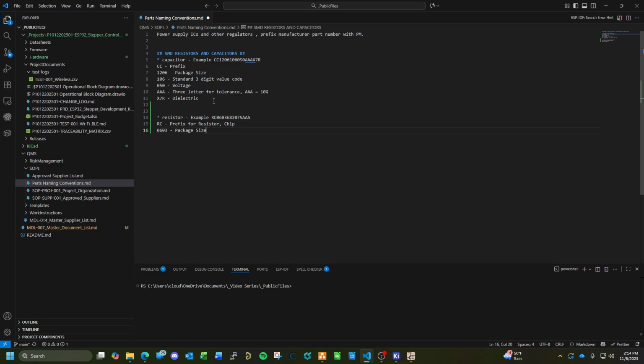So for things like resistors, it's the same thing as most typical chip capacitors. You're not buying mainly for brand, except if you're looking for cost savings or a favorite brand. You're basically buying these parts based on specifications: their resistance, their package size, their power rating, and any other special things you want to note.